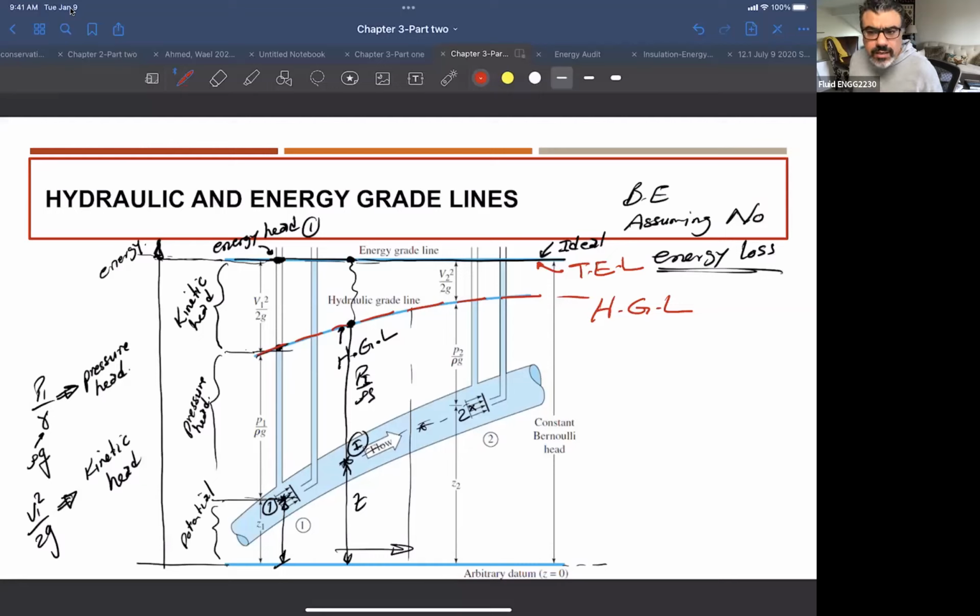So do you expect the design of these pipelines to be the same? Do you expect, for example, the thickness of this pipe to be the same or not? Of course not, right? A location where the pressure is very low doesn't need to be very thick. If you are designing a pressure vessel, or a pipeline or a cylinder, and the cylinder is subjected to an internal pressure, the thickness of the pipe will be somehow related to the pressure inside.